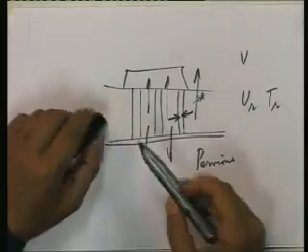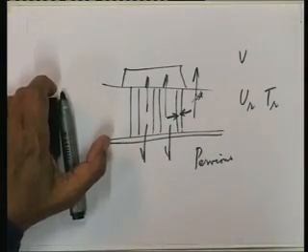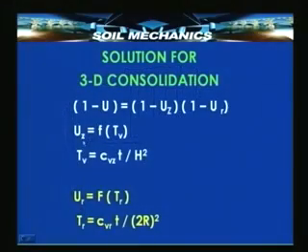Now, if you take a look at this equation, you will find that vertical consolidation, average consolidation is given by UZ, Z standing for vertical now. I had used the same notation UZ earlier to denote the degree of consolidation at depth Z, whereas here this UZ stands for the average consolidation in a layer, but in the vertical direction, that is vertical direction is taken as Z.